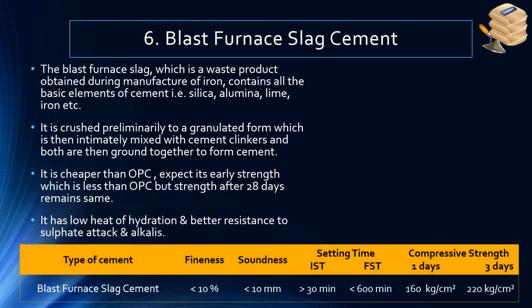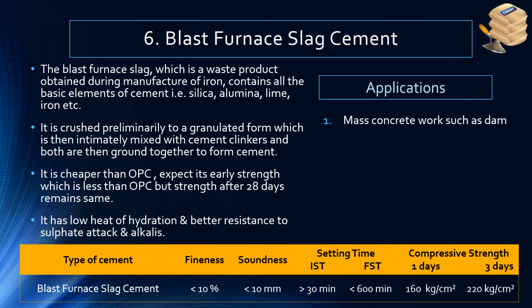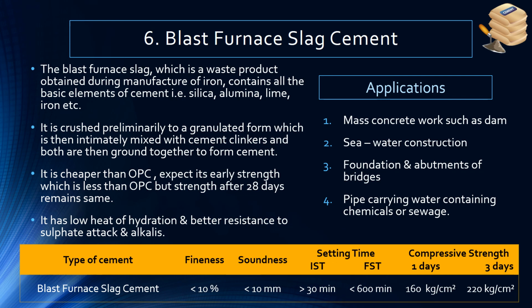Then properties of blast furnace slag cement are fineness less than 10%, soundness less than 10 mm, initial setting time more than 30 minutes, final setting time less than 600 minutes, compressive strength after 1 day 160 kg per square centimeter, compressive strength after 3 days 220 kg per square centimeter. Then applications: mass concrete work such as dam, seawater construction, foundation and abutment of bridges, pipe carrying water containing chemicals or sewage.